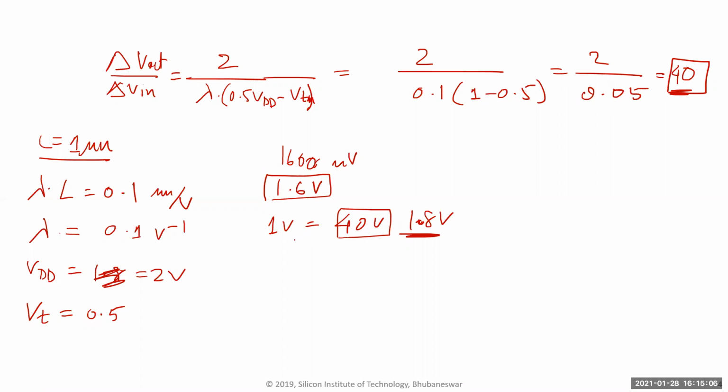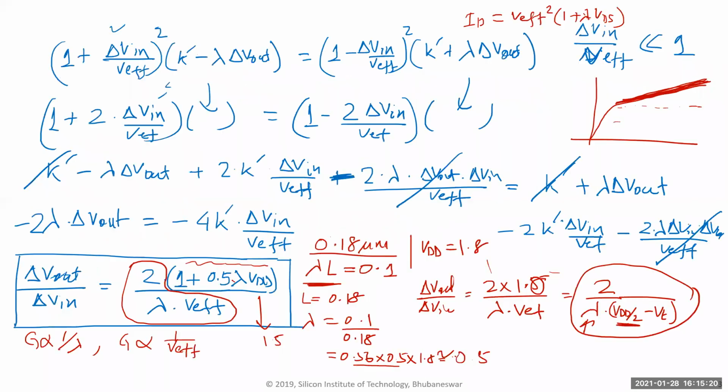And also just remember, so now let me ask you this. We said for a small delta V in, this whole analysis is valid. How small? How high can I go and still use this analysis? So this number here, 2 lambda by VDD, how high a delta V in can I go? How high, and still use this? VIH minus VOL. Okay, what else? Who can, people on the call, anyone can guess how much?